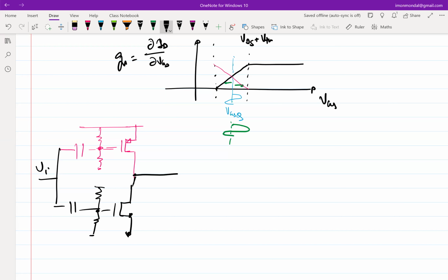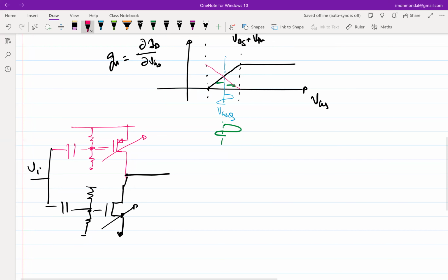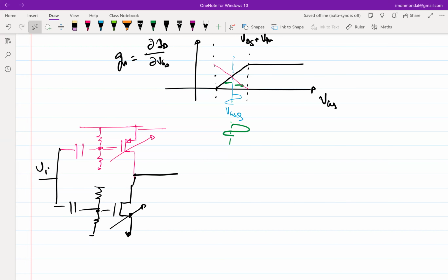So typically, if one uses this, what is generally done is to have a bank of PMOSes and a bank of NMOSes. By bank, I mean that you have multiple of them connected with switches, and you turn on the switches based on your requirement.